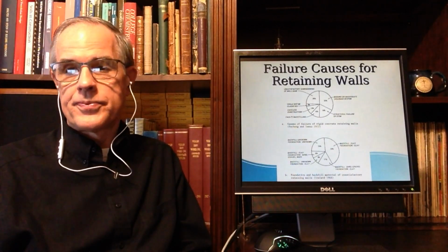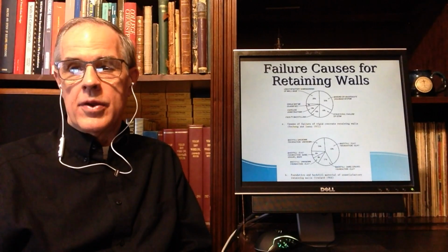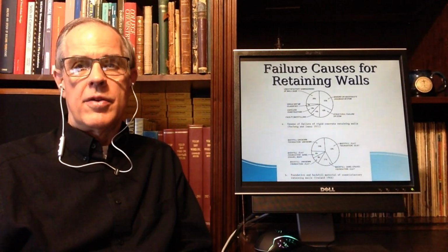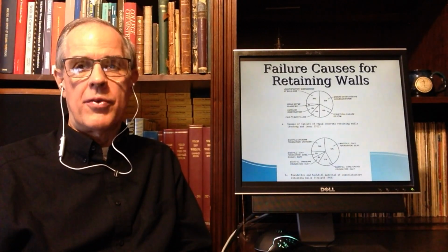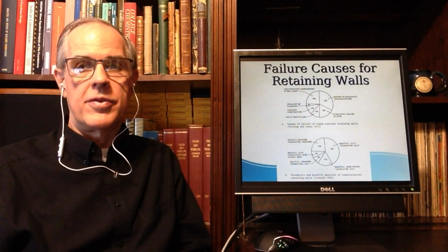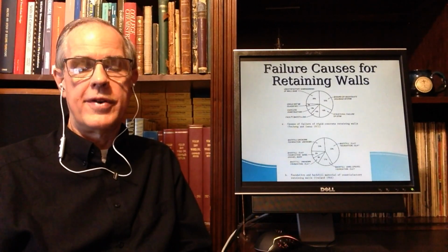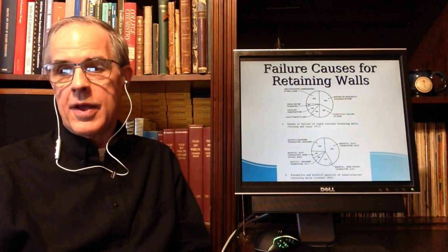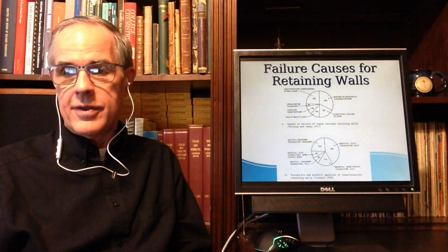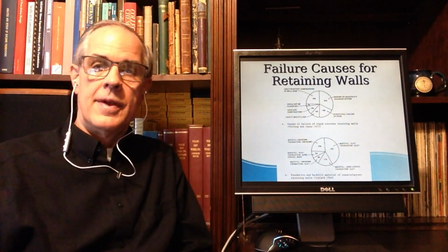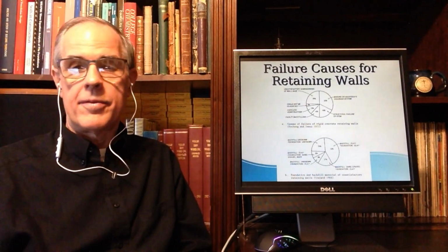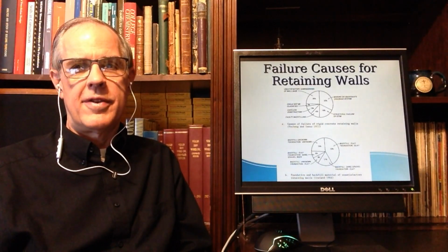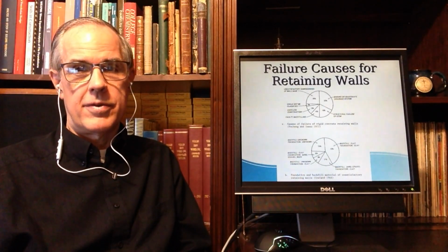Right after that is the unsatisfactory definition of wall base. But the need for drainage behind walls cannot be overstated. You can design the nicest wall in the world, but if your water table builds up hydrostatic pressure behind the wall, you're going to have problems. And the reason why is the second part of it, at the bottom: the backfill is clay. Clay backfills are frequently unavoidable with retaining walls, but they're never necessarily desirable with retaining walls.